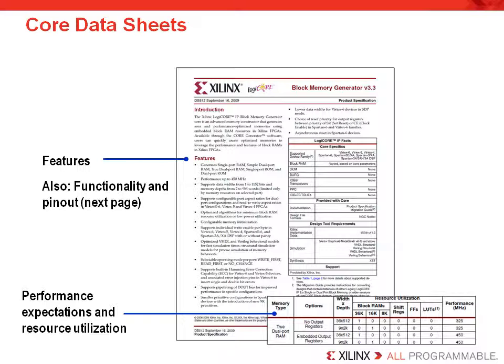Many of the cores provide performance expectations. However, the table does not always describe every device or supported speed grade. In case the core has a defined performance specification related to an industry standard timing specification, that information is provided in detail. But not all cores, especially not the block memory generator, have a performance requirement because it's just a block memory. Device utilization for various core configurations is also provided where possible. In this case, knowing the number of block RAMs used when a large memory is defined is helpful if you are trying to manage your block RAM usage.